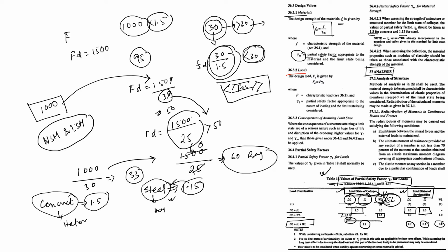Why 0.8, 0.8? Serviceability means we are using the structure. When we create a structure, we can take the maximum load. But when we use a structure, it is not necessarily like that, that the structure has its full load. That is why imposed load is 0.8 and wind load 0.8.